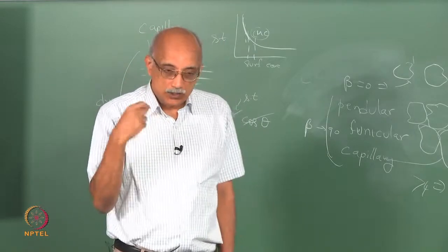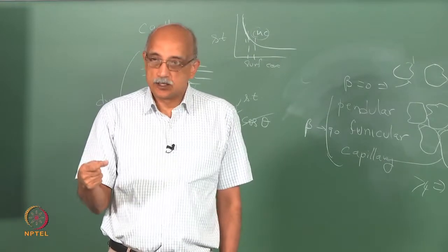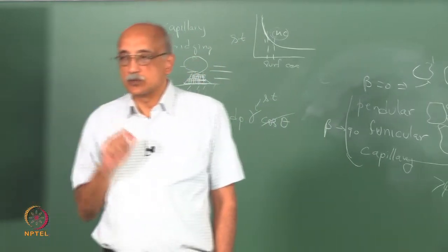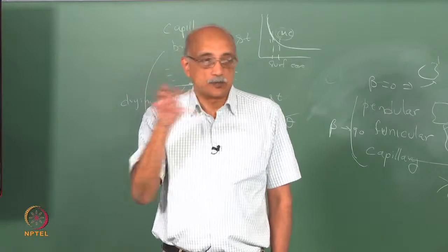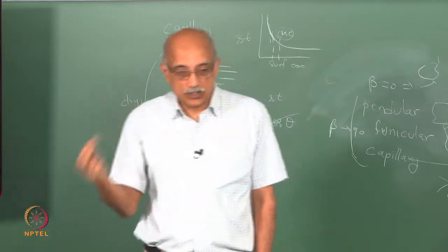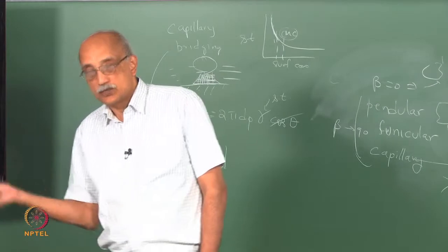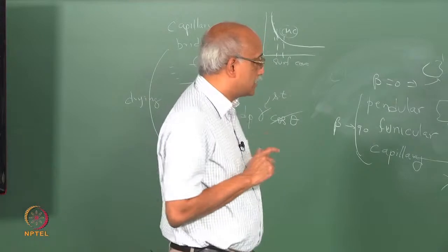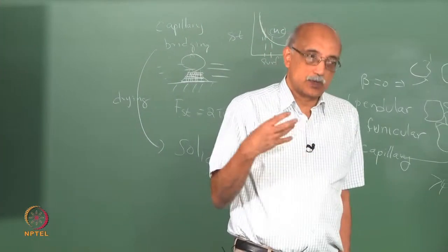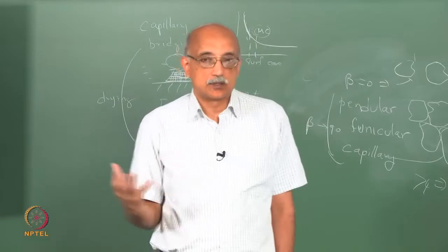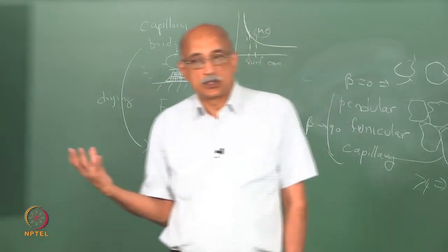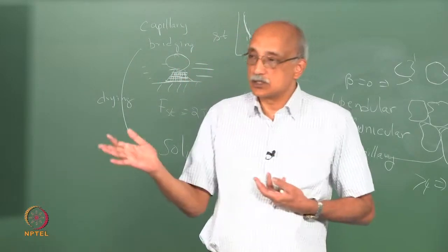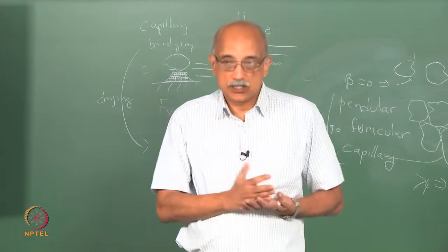So the computational time required can actually increase in flows that are less cohesive. In flows that are more cohesive, you do not have to deal with individual particles, you can essentially deal with groups of particles. So in terms of computational effort, cohesive flows are easier to handle. But in terms of accuracy, your ability to predict flow, a non-cohesive flow is much easier to predict, particularly in terms of the gross parameters such as pressure drop, energy consumption and so on.